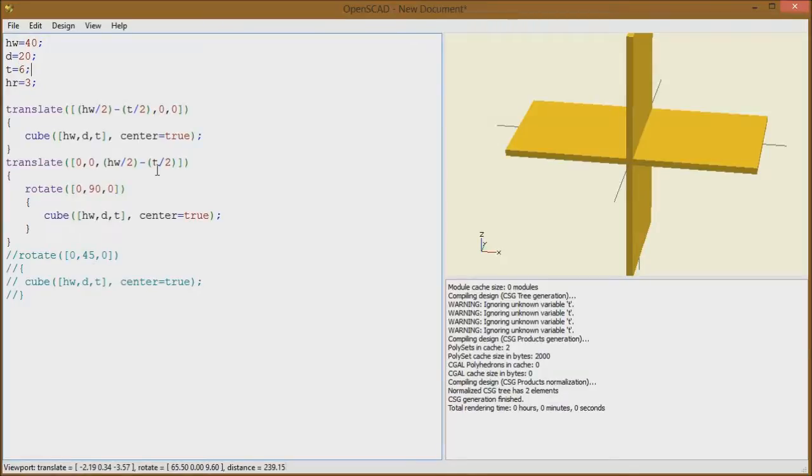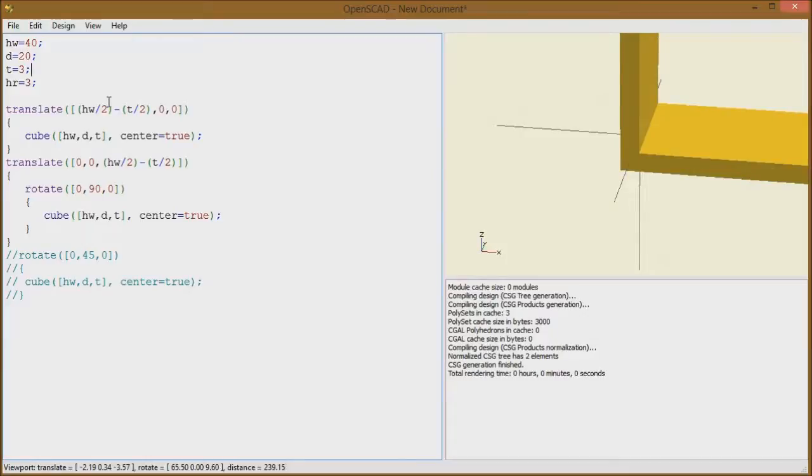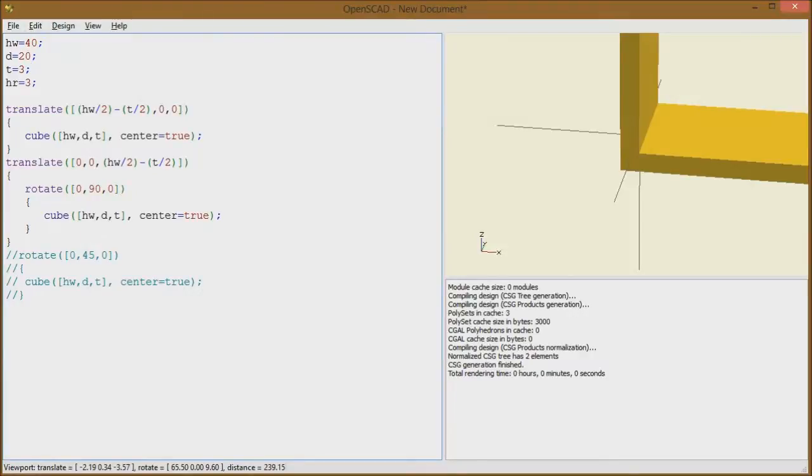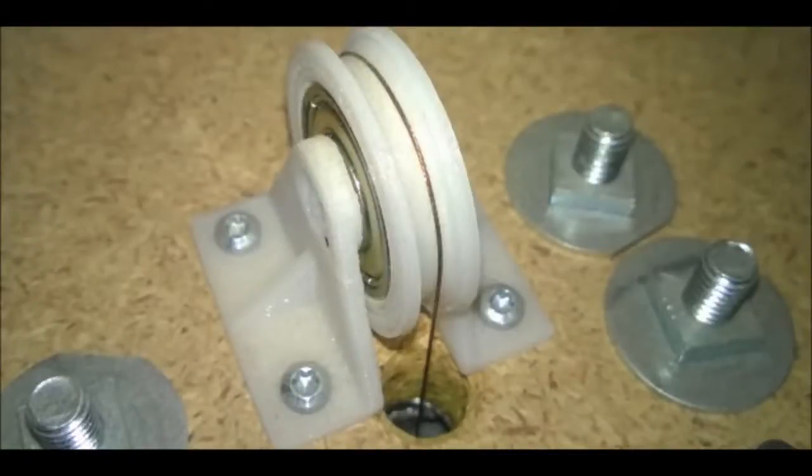6. In my experience, I've seen that for 3D printing, you probably don't want to go with parts less than 3 millimeters thick, because then it gets really, really thin. So to give you an idea, this part is part of my printer, and these walls are all 3 millimeters thick.